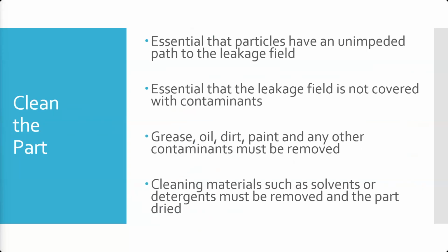Grease and oil can actually be thick enough that the magnetic field jumps inside of it, but never comes to the surface. Right? This magnetic field with little tiny cracks, it's not jumping very high off the surface of the part. And so if you have a thick enough layer of grease or even paint, that field may never make it to that surface. It leaves the surface of the metal structure, but it never gets above whatever's on the metal. And so we have to remove those.